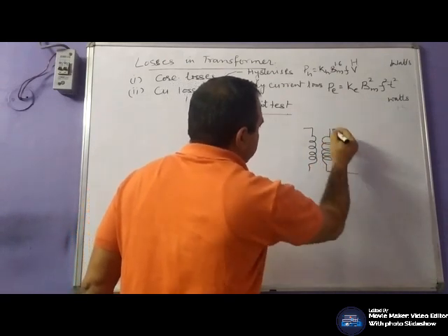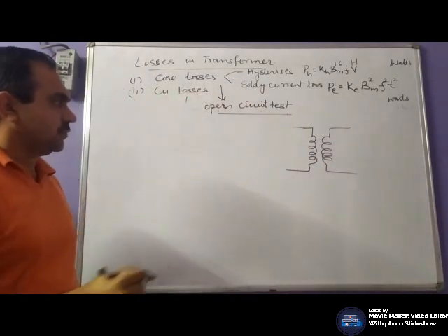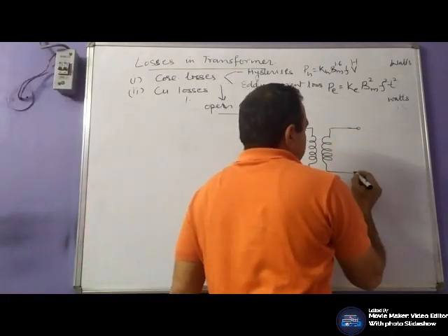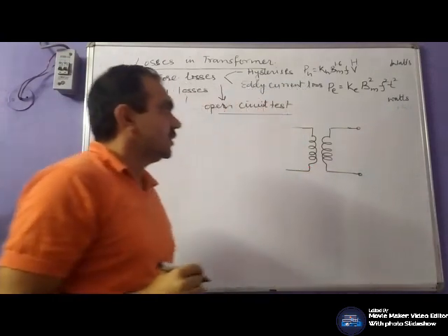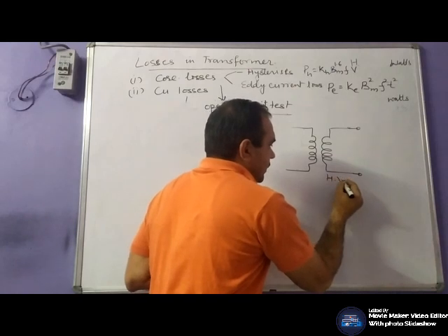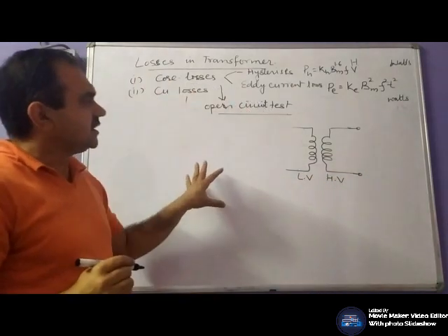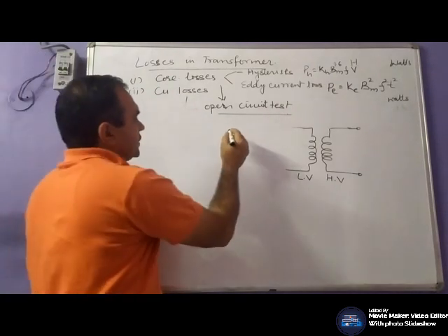One side is kept open. Generally we keep the high voltage side open and the apparatus is connected on the low voltage side.